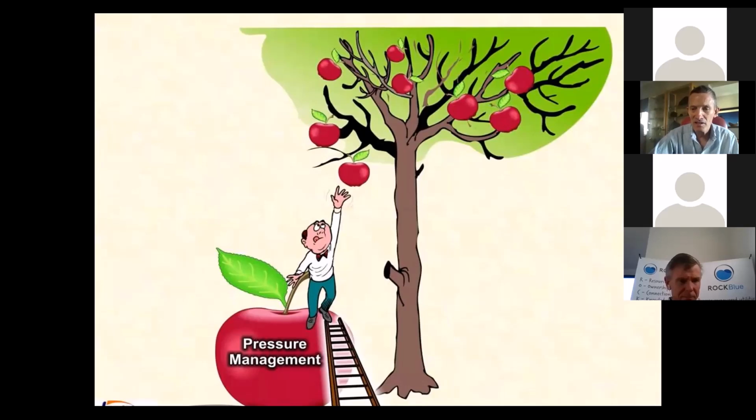The paybacks on pressure management can vary, typically from the 400 or 500 installations that we've designed and built. Typically anything from a month to 2 years would be your payback from a pressure management installation. And generally we are in the 3 months to 6 months range, but it can be as low as a month, it can be as high as 2 years.